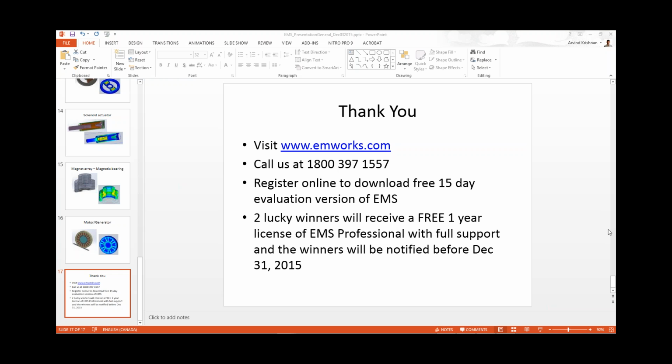However, there is one thing that you can do. EMS gives you the loss in terms of watts for your different components. You can take that value and apply it to the entire body inside your SolidWorks Flow Simulation. It's probably not the most accurate way of doing it, but nevertheless it can give you an idea of what type of cooling can happen inside your model.